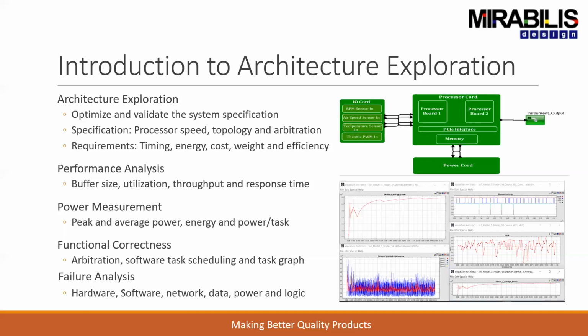Then of course, what is the efficiency or the quality, be it your software scheduling or the power consumption based on certain arbitration schemes that you're deploying in the memory, or a very important aspect, buffer management. Do you want first come, first served? Do you want to reorder based on priority? Do you want to do last come, first served?